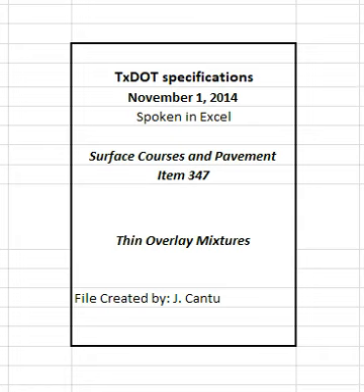The engineer will grant the contractor conditional approval of JMF1 if the information provided on the paper copy of JMF1 indicates that the contractor's mixture design meets the specifications. When the contractor does not provide Hamburg wheel test and overlay test results with the laboratory mixture design, 10 working days are allowed for conditional approval of JMF1. The engineer will base full approval of JMF1 on test results on mixture from the trial batch.